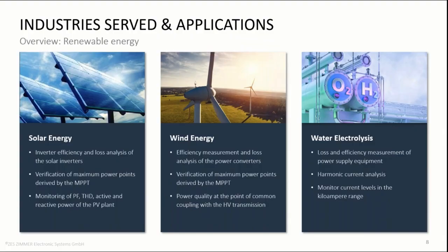The role of a power analyzer here is the same, creating an efficiency map for different maximum power points, and furthermore, one can use power analyzers to verify the quality at the point of common coupling with the transmission grid.